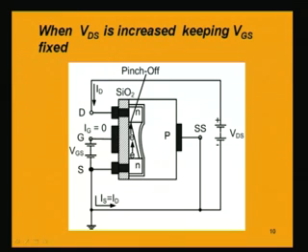So, if we travel from the source upwards and reach the drain, at this point this voltage VGD, that is between gate and drain, which is nothing but VGS minus VDS, will be least at the drain.